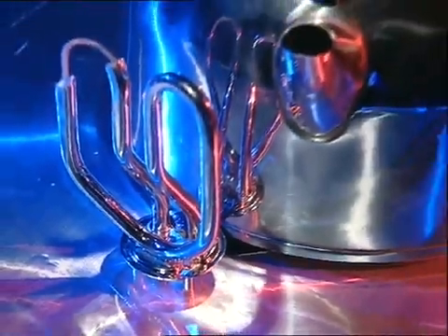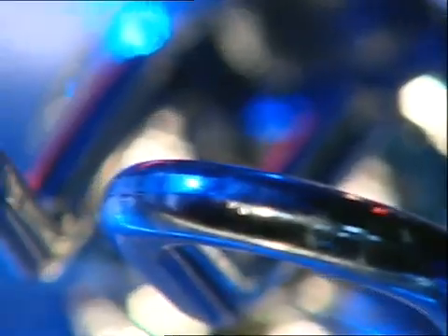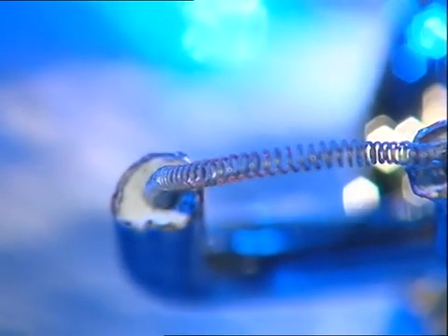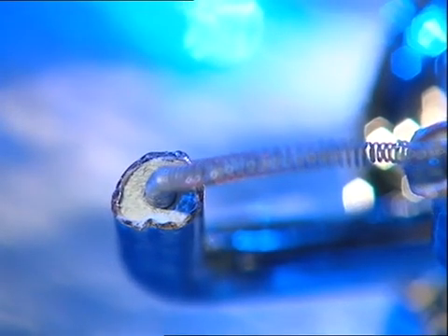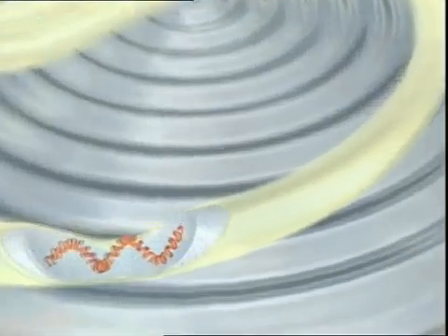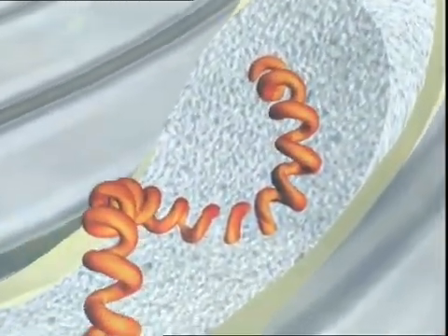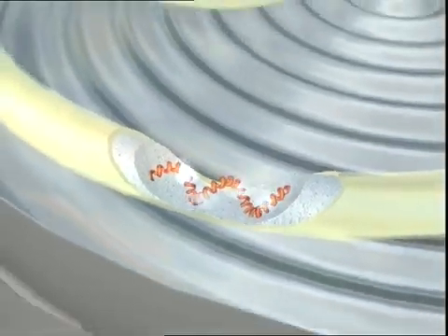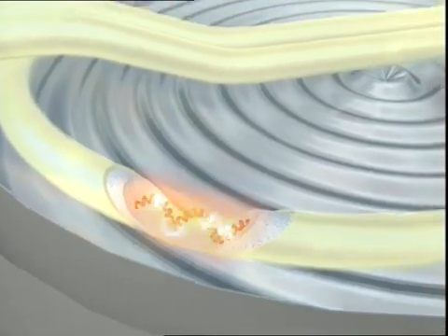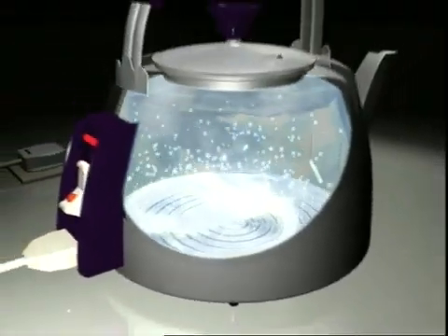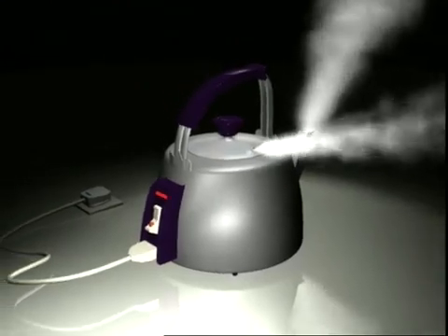The heating element in the kettle is made up of a metallic tube. If we cut open the tube, we can see that the tube encloses the heating wire and that there is a layer of white insulation between the tube and the wire. The purpose of the insulation is to separate the heating wire from the metallic tube to prevent electrical leakage. When an electric current passes through the heating wire, it generates heat, which is conducted to the metallic tube. The hot metallic tube then heats up and boils water in the kettle.